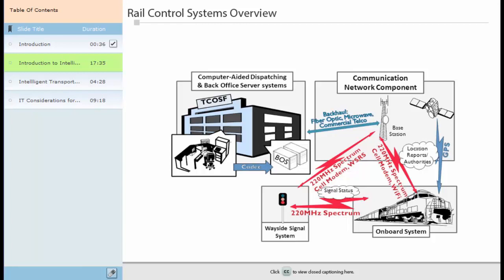An effective PTC system is able to monitor the location and speed of trains in order to enhance safety measures already taken by the engineer. If an imminent collision is detected, warnings to slow or stop the train are activated. If warnings are ignored, the PTC will take control of the train, applying the brakes until the desired speed is achieved.